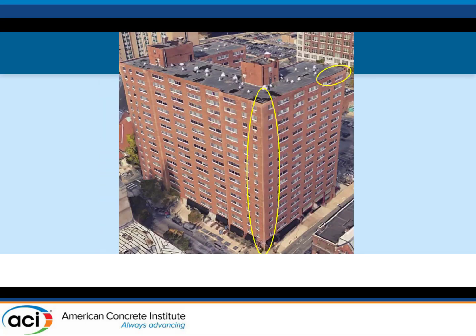Right? So you take that same concept of shortening of concrete, and that was only a 6-story building, 100 feet. Now we put it on an 18-story building. The order of magnitude is even more severe. I think the thing that they had going for them in this building, they really did have the gap between the brick masonry and the underside of the relief angle lines. But at the corners, as you see there highlighted in yellow, that's where we found the most differential movement. Again, an 18-story building, those columns shorten to a certain degree. And when you don't allow the brick to expand at every floor, it just stacks itself up.